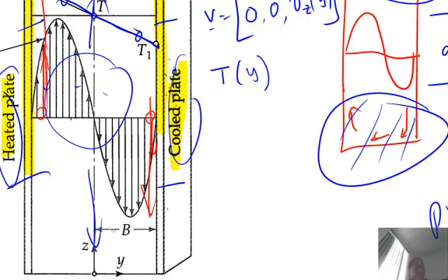Saying that it'll appear to have flow if there's a concentrated heat source. If there is a concentrated heat source from both sides, the specific question that you were asking, and there is no gravity, then what happens is as you increase the temperature, the volume is constant, so the pressure will go up.